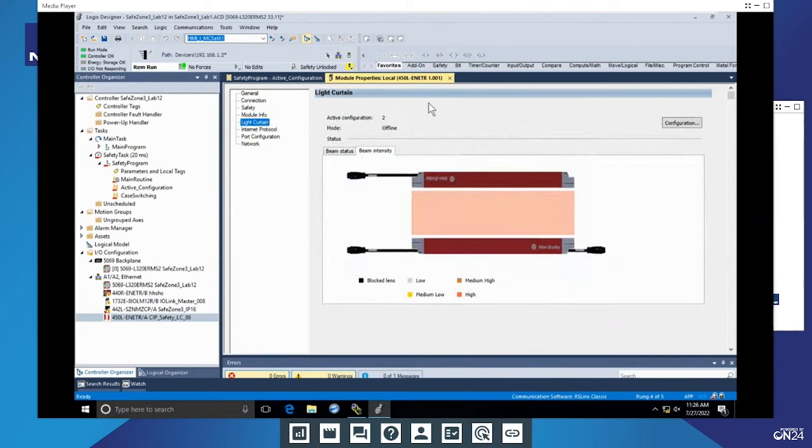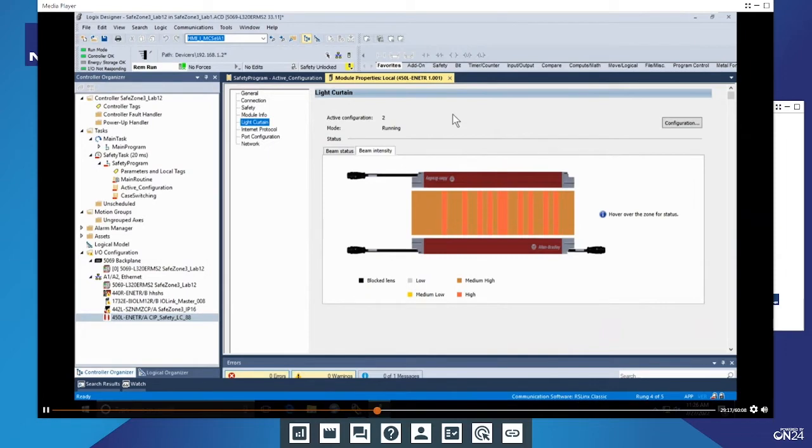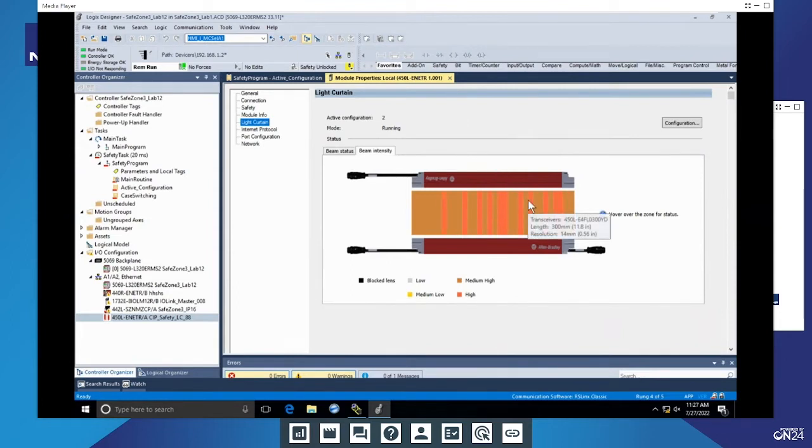I'm going to focus on what a lot of us truly value. Let's start with something called beam intensity. Traditionally, when, say, a contractor calls us from your plant, you are going to wonder, oh no, these light curtains definitely go under. What's going on? Why are they tripping falsely? This is where beam intensity comes into play. Say, for instance, you've got a network system and your light curtains are on Ethernet. You'd log on using your Studio 5000, you'd go online, and then you'd get a live demonstration of this.